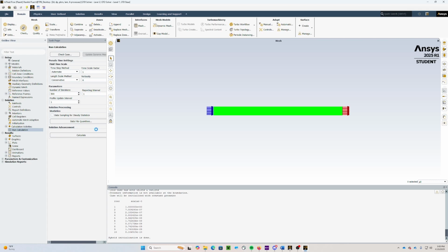If you run too few, like if you only ran 1 iteration, your residuals may be too high and you may not get accurate results. If you run too many, you may achieve accurate results at fewer iterations, so now you're just wasting computation and time. So 500 seems like a good number. I didn't optimize this number, it just seems like a good number to get decent results out of it.